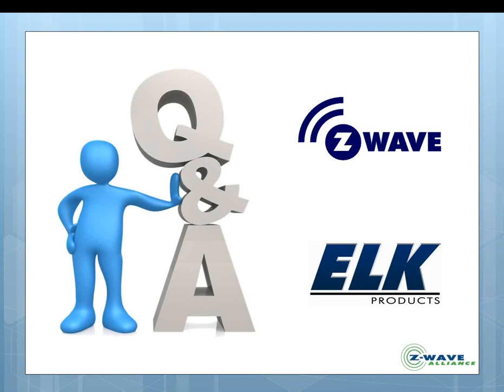Yeah, and Amy has a great point there that if you do that, or even if you're just designing an all Z-Wave network, we do need to make sure that we have line-powered devices between the controller and the door lock and the thermostat, and that the device that's closest to the door lock or the thermostat, the device that's closest to the beaming device, also supports beaming. The ones in the middle don't have to.